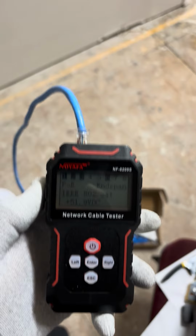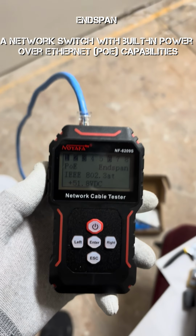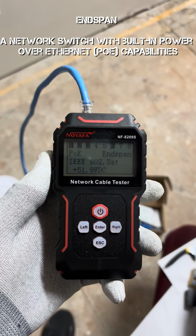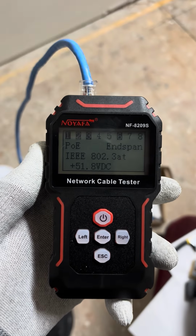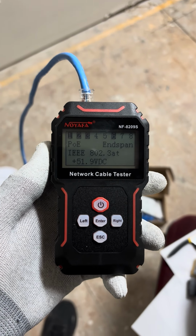All that is to say it's an end span. When you see the pins 1, 2, 3, and 6, that means it's an end span, and the end span is most likely a switch that's delivering Power over Ethernet.